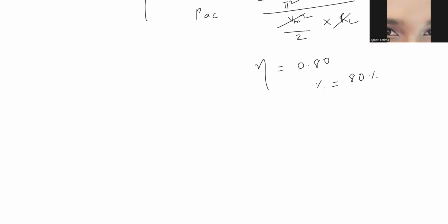Next, very important: you have to find the ripple factor. How will you find the ripple factor? What do you mean by ripple factor? Ripple factor means, whatever DC component I'm getting, DC output, I have to remove the AC from that output. It is denoted as gamma. Gamma is equal to the formula: square root of VRMS square minus VDC square, divided by VDC.